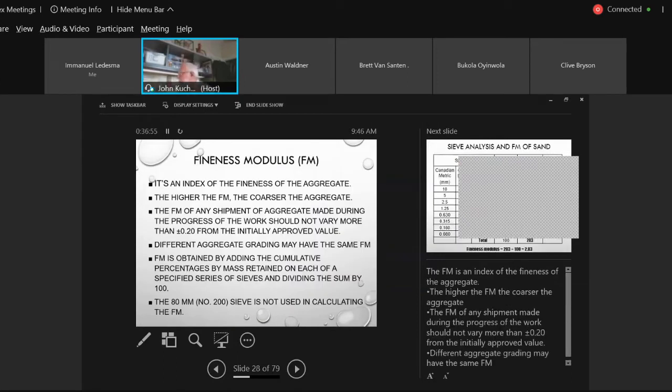Okay, the fineness modulus. Did Natalie explain to you guys last year why when we calculated a sieve analysis, we had percent retained and then we had cumulative percent retained, which you don't need to calculate percent passing, right? It was just a good check to see, did you get back to 100% retained? Anybody? There's also another reason why we're doing it. I set up a lot of those sieve analysis forms for a simple reason. When I came from industry, we always did cumulative percent retained for the simple reason we tested lots of concrete aggregate.